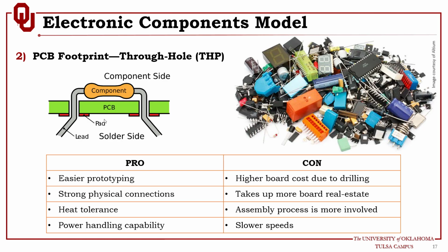It's very interesting. I have used one of these machines like 6 years ago, 7 years ago, even more than that actually. So the advantages of through-hole components: they are good for prototyping, because it's a big component, you can easily deal with it, remove it, put another one, and so on. And they have very strong physical structure and connection to the board as well, because they have to go through the hole all the way to the other layer, and you solder them from the other layer, and they count on this lead, which is strong enough to hold the whole board.